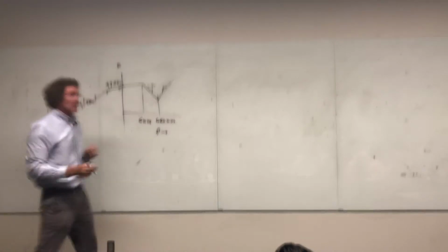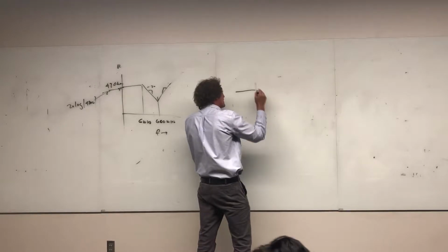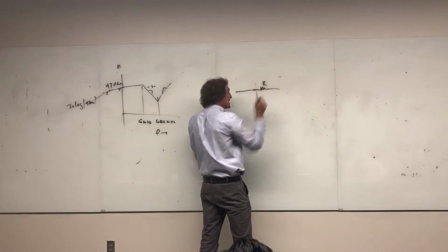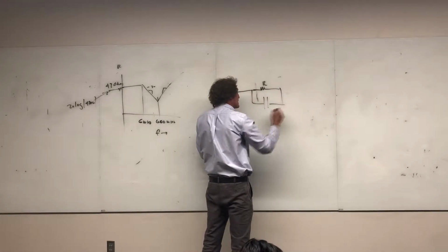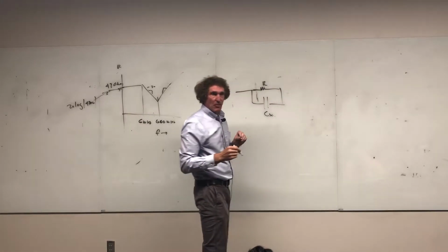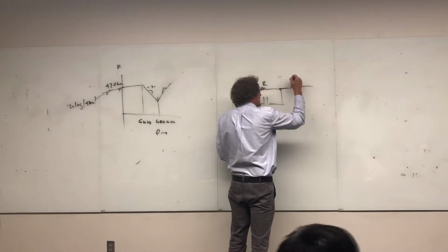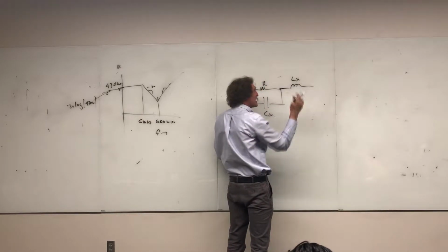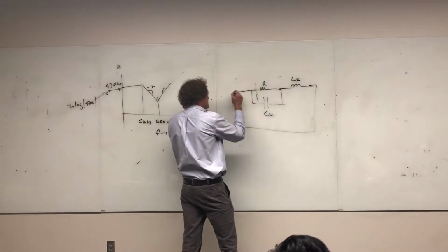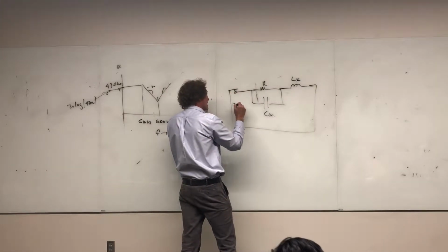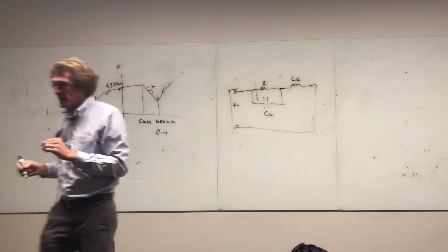If you remember, the standard model for a resistor is what? You start with the element itself, the resistor. That's R, given as 4,700, right? Then in parallel with that, you have some CX, something you don't want there. Then in series with that, you have some LX, L of the leads. And this is the actual impedance that you're looking at, right? Correct, class?